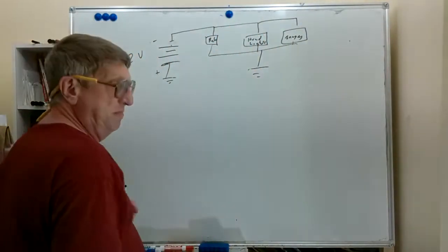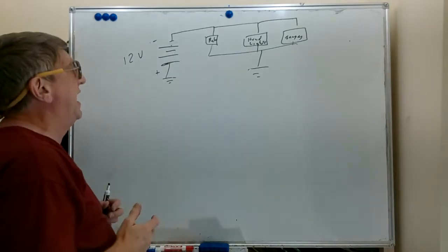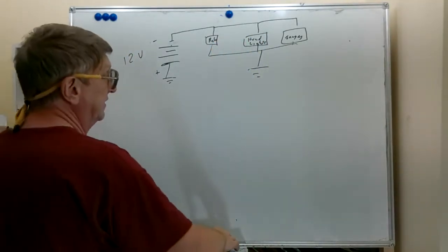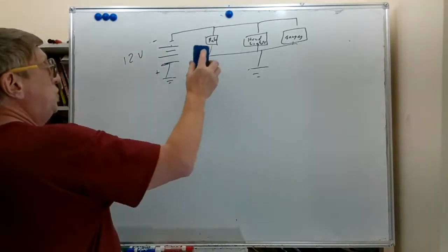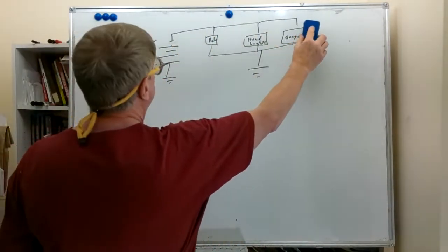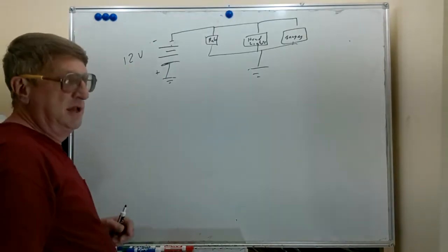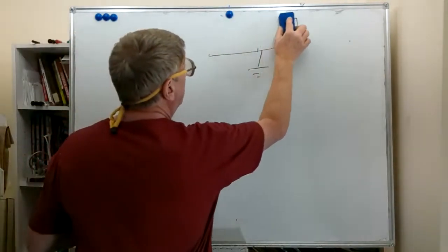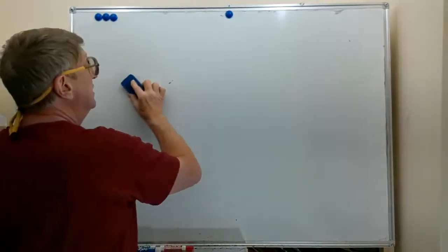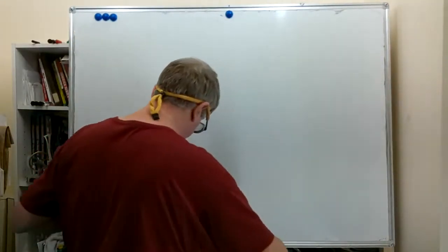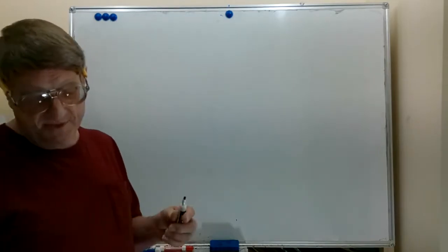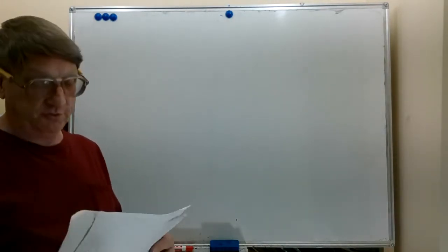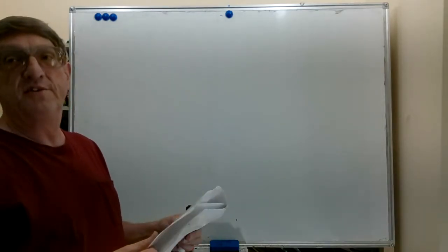Well, the headlights don't matter. They're a light bulb. You can power them any way you want, but the radio and the gauges probably would need to be connected correctly. So whichever way the manufacturer designed this is going to work. We've standardized on the negative ground, but it's not because the positive ground cannot work. It's just to keep everybody on the same page.